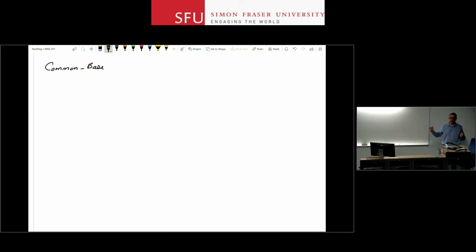Obviously, the input cannot be connected to the collector. We discussed it before. So collector is the output and the emitter is the input. So if I draw the circuit, the AC circuit, it's going to look like this. You have your input attached to the emitter, and output is from the collector. And obviously, we use a resistor here to convert the current from the collector into a voltage. Okay? So this is the circuit.